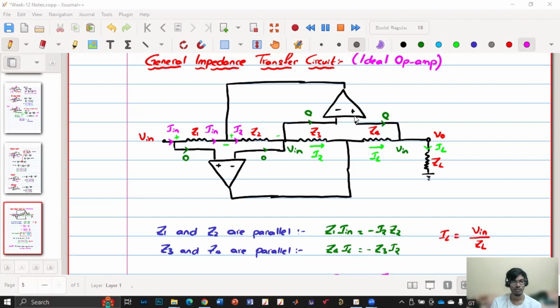Not only thickness, right? Yes, the thickness of the inductor as well as the area will increase. And in many applications, the inductor will be that constraint for space. So nowadays, people who want to reduce that space are trying to concentrate on how to reduce the size of the inductor, because the height also is posed by the inductor.